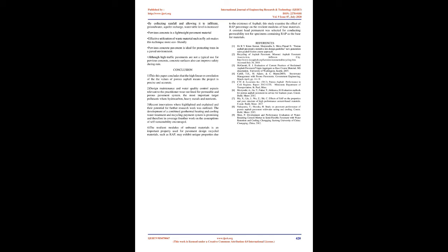E. Porous asphalt pavements are an alternative technology that differs from traditional asphalt pavement designs in that the structure permits fluids to pass freely through it, reducing or controlling the amount of runoff from the surrounding area. By allowing precipitation and runoff to flow through the structure, this pavement type functions as an additional storm water management technique. Benefits include groundwater recharge, improved storm water management, improved skid resistance, reduction of spray to drivers and pedestrians, as well as a potential noise reduction.